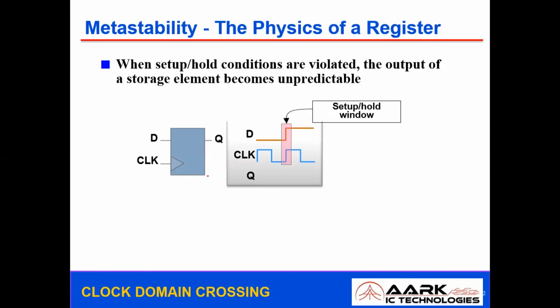Now you can see here, there's the clock and there's the clocking edge. So during this rise edge of the clock, your data is stable. Let's say for example you are getting data like this, so during this window your data is 1. So it is stable, it is not changing. If it is not changing, that means it is passing the complete setup and hold times. Therefore, we can avoid the metastability issues.